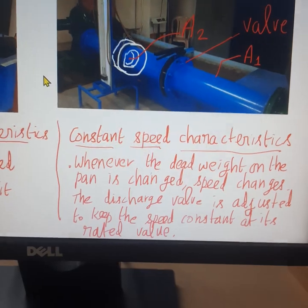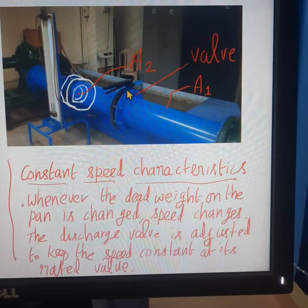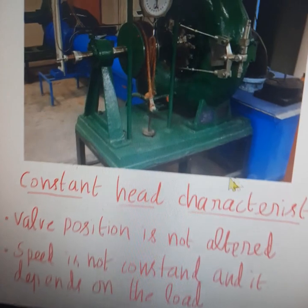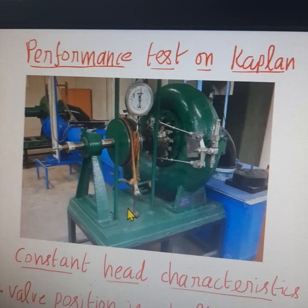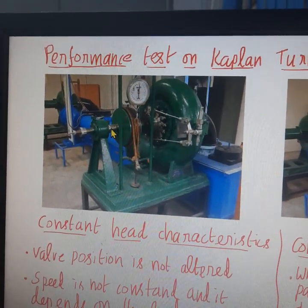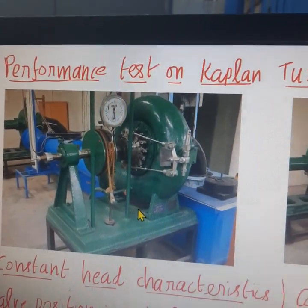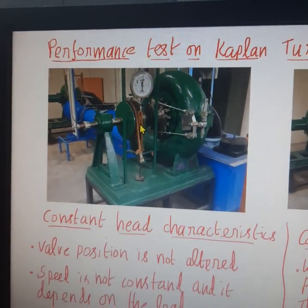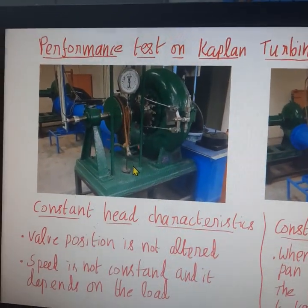When you want to run the turbine at a constant speed, the valve position will be altered depending upon the loading. See, the turbine is loaded using dead weight placed on the pan. When the turbine is run under constant head, as the load is removed or added, the speed of the turbine changes. So we have to determine the speed of the turbine at each and every loading level when you want to run the turbine at constant head.